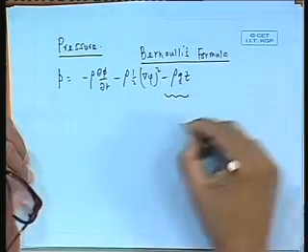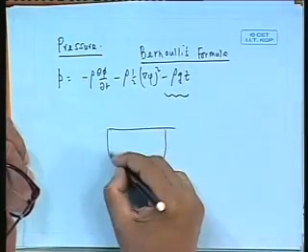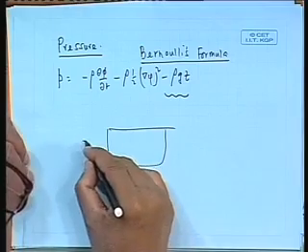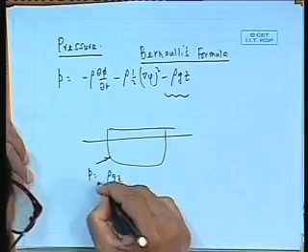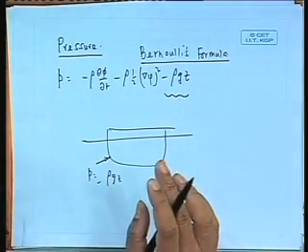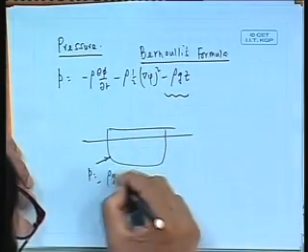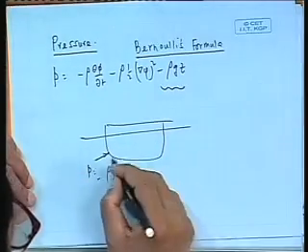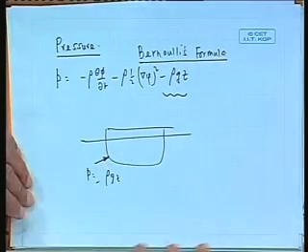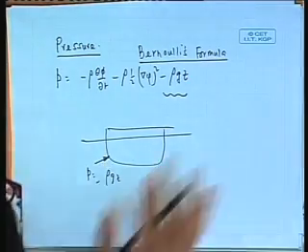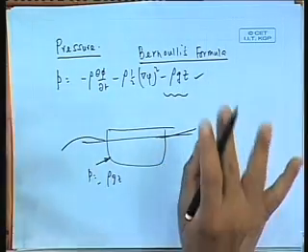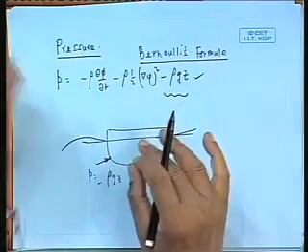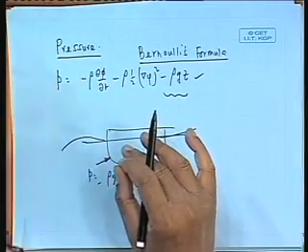Now earlier, I have this body here. I want to find out what is my pressure. This is my water surface. I said that this pressure is given by rho g into z. If you recall, the pressure acts in the normal direction of this magnitude. Unfortunately here I have got waves now, so I have this pressure of course always there, but now there is additional pressure. Why? Because the water is not static, water is moving.